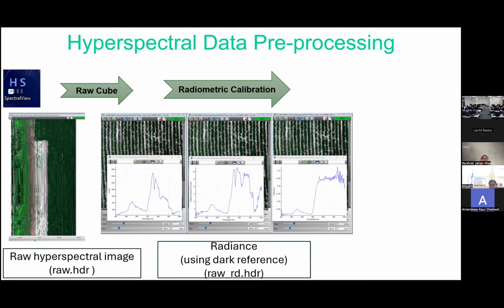The sensor has a cap, because the sensor is a camera, right? So the camera has a cap. We have to take one image with that camera with the cap on. That means it will be a black image, just nothing, just a black image. This is the first part, to cancel noise. Why do we take that black image? Because every sensor has its own limitations, its own noise. And when we take images outside, there is also lots of noise because of environmental things and everything.